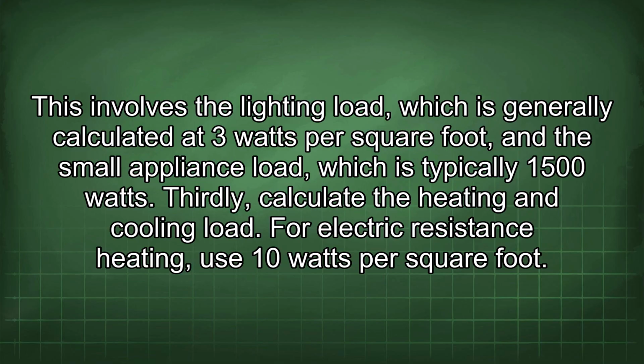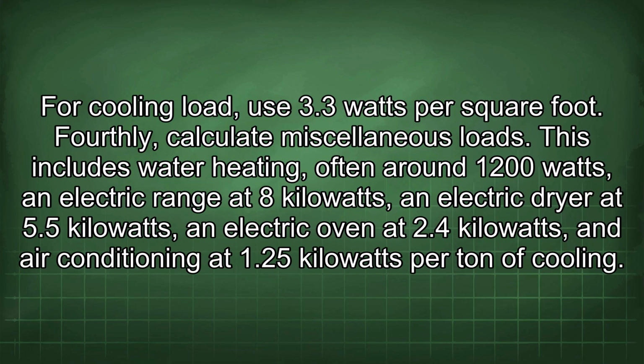Thirdly, calculate the heating and cooling load. For electric resistance heating, use 10 watts per square foot. For cooling load, use 3.3 watts per square foot.